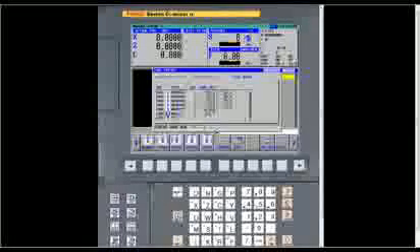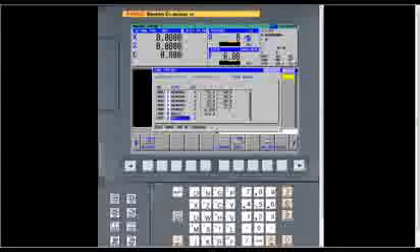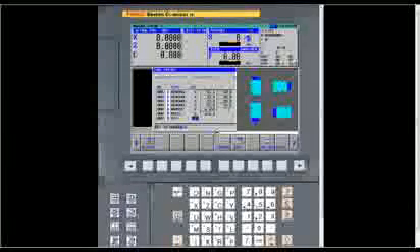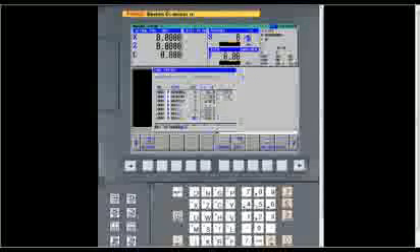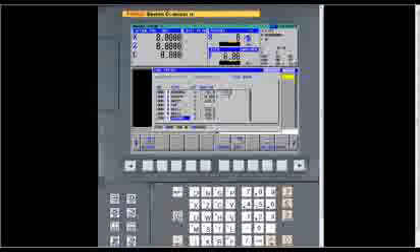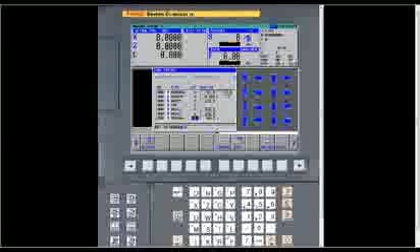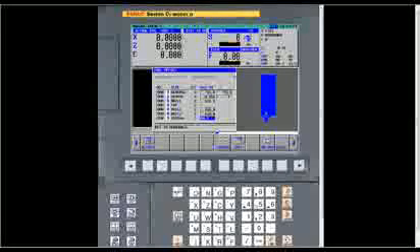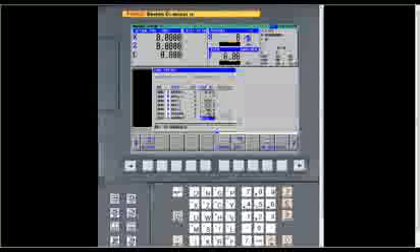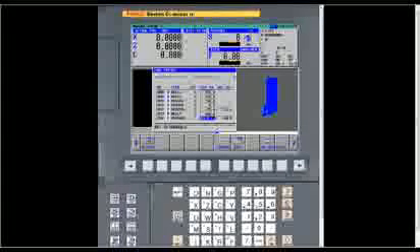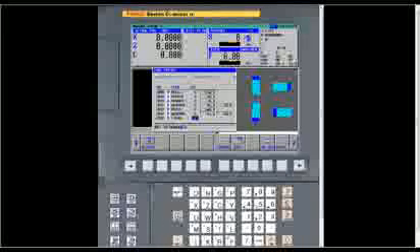In a tap, you don't have to put a lot of information, just the tool type has to be correct, and then the orientation. On a horizontal lathe, it's typically going to be a number 2 for the left spindle. Then for drilling, threading, you don't have to put a lot of information, just the right tool type. Again, the setting based on what your tool looks like, and then the angle on your insert. Very simple. But it's critical that you get this information correct beforehand. And a chamfer tool, general, and then a flat end mill, again, just the orientation.